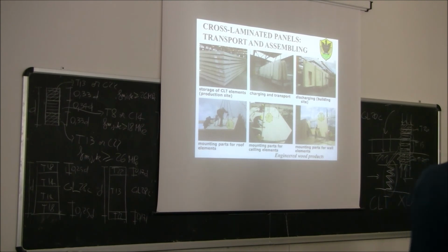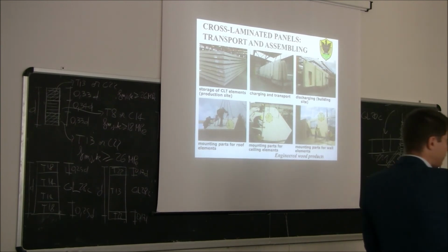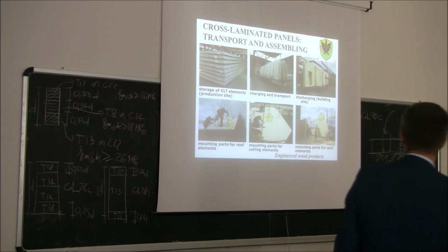So in the end, this construction is made of several panels, and those panels, of course, need to be kept together, otherwise the system will be static and independent. We will discuss later on how we can connect these panels together and how we can calculate the connectors, with screws and nails, in order to ensure that the building is stable under vertical forces and under horizontal forces.